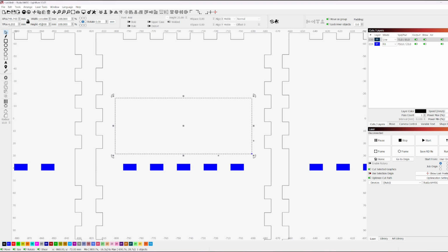Let's go ahead and make it taller. Here's another tip. When you're making adjustments, you can use an anchoring point. So in this case, I don't want it to move from this bottom edge because we have it aligned where we want it to be, 8 millimeters up from the floor. So I'm going to set the anchor point to center bottom. That way this bottom axis doesn't move along the box.